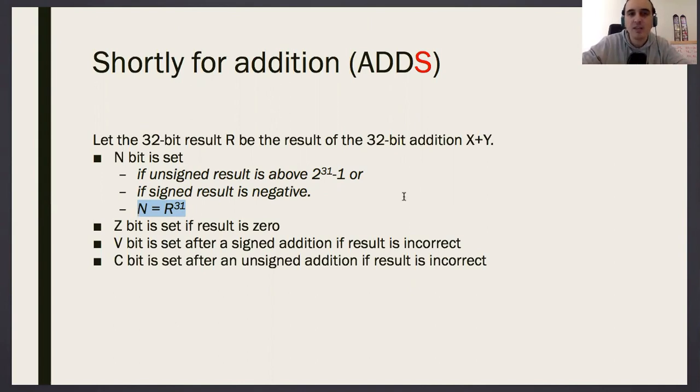If all bits of the 32 bits are zeros, you don't care about carry. Carry could be 1 or not. The residual, you don't care. If the 32 bits are all 0, then Z bit is set. Okay?